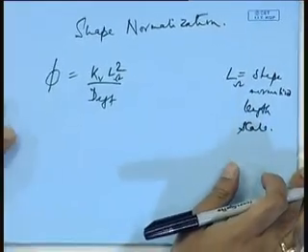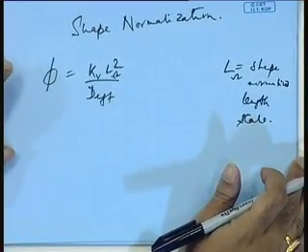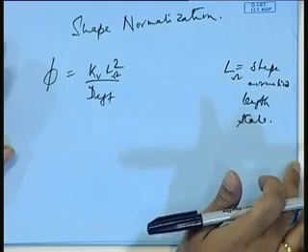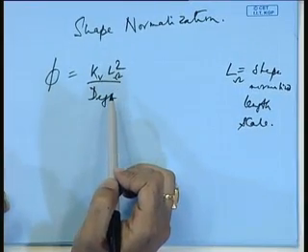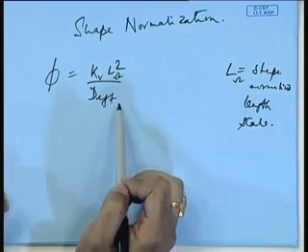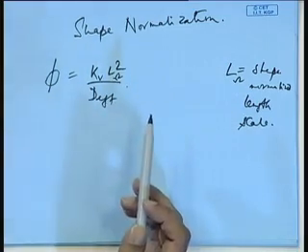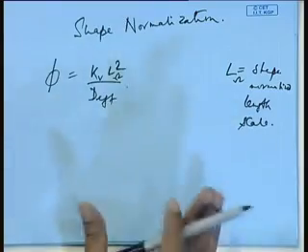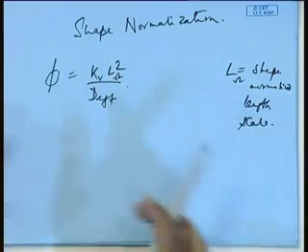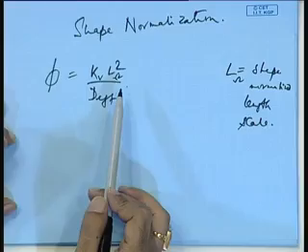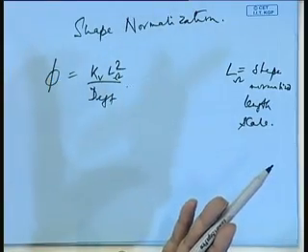You see what I am saying? So, in the definition of phi square, this is correct, right, Lisa? The L that you have, the length scale that you have, is now a shape normalized length scale. Next class I will show you what is r over 2 and r over 3 for cylinder and sphere, and so you can come up with what the shape normalized length scale is. So, the idea is that irrespective of what form you have, you can transform it into a slab, right. Is that a perfect answer? No, it is not a perfect answer, but the advantage is it is very close to the perfect answer.